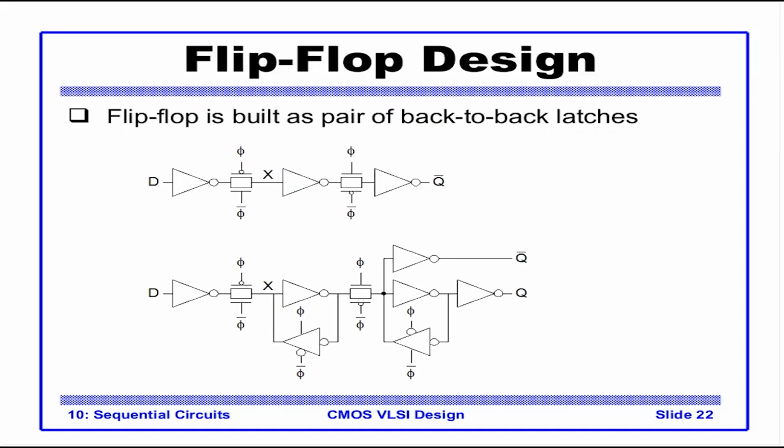Now let's look at the flip-flop. Again, going back to Morris Mano, basic digital design, a flip flop is made using two latches connected back to back together, with the clock being inverted to the first one. This is called a master slave configuration. So this is an example of that.